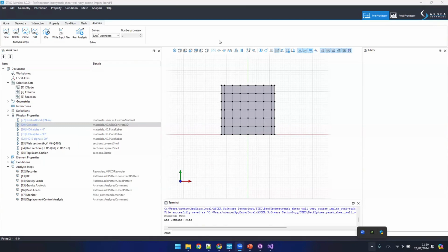I know just fiber, but do you mean a fiber that takes into account both concrete and steel? Or as I show you here, a fiber cross-section, layer cross-section in this case, where some fibers are made of concrete and some fibers are made of steel, okay? And the section will give the combined results. So this one, yes, they are already in OpenSees. The concrete, ASDConcrete3D, is already in OpenSees.